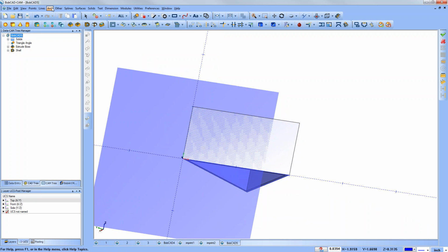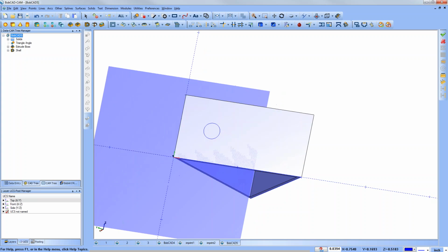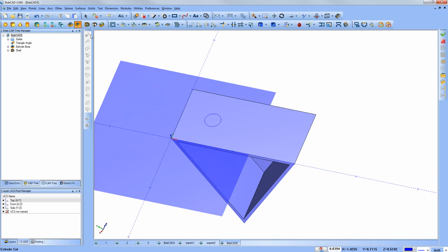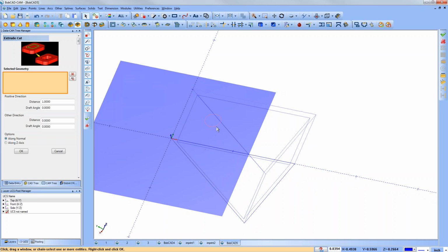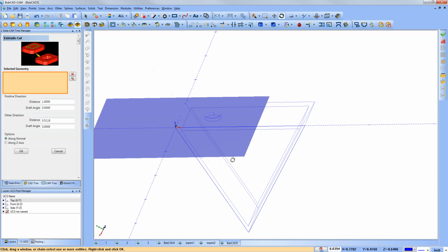So if I wanted to create an arc at coordinates, say the radius is something like that, and then x of half an inch, that may work, y half an inch, okay, good enough. So I got a shape here, and then I'll use my extrude cut, again S for shading. I'll see if I can bring this down through here. If it cooperates with me, it should.